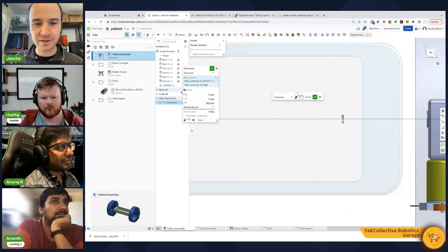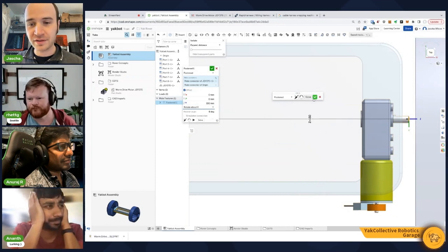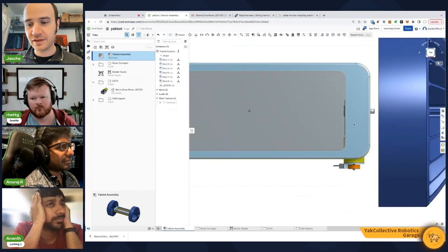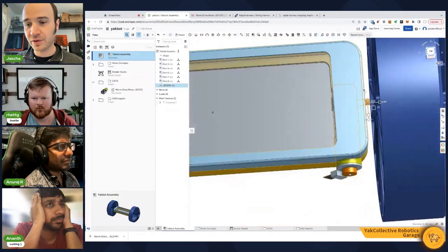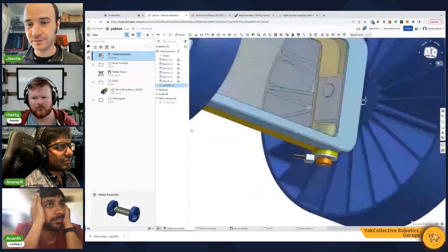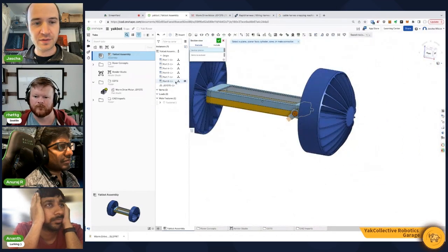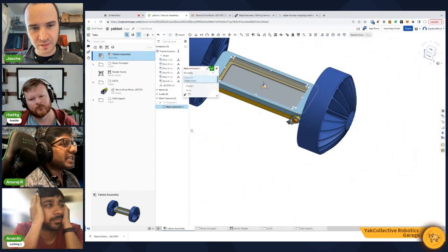But generally, I feel like I'm saying conflicting things. Generally, for initially blocking stuff out, just dragging it around is cleanest and most efficient. Okay, so this is an example of where the motor could be mounted in the final assembly. And we can start to do things like section views and look for interferences. So now the motor is fitting exactly to that box.